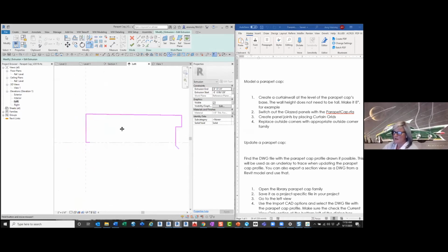This also makes it nice when you're dimensioning in Revit. You don't accidentally pick the wrong thing. It looks nice to have those curved radiuses on there, but that's one of the things Steve said is no radiuses, and it's a good point. It's a good idea. And it keeps it simple. It's less drafting, it's less work. So once you've got your lines all updated and everything's closed off, you can just hit that green check mark, which is finish edit mode.